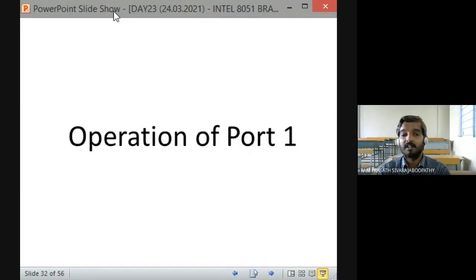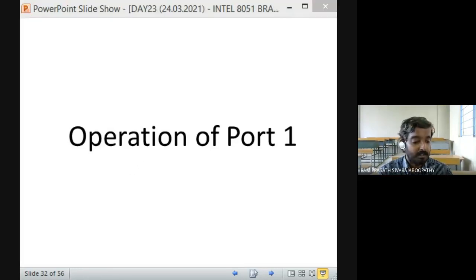Very good, Karthikeyan. Kindly correct it, Kavyasri. It is not S bit. Set bit. SETB. Okay. SETB, then the port pin, say for example P2.0. Yes, this is an example. What happens when this instruction executes? The P2.0 pin will go to logic 1.